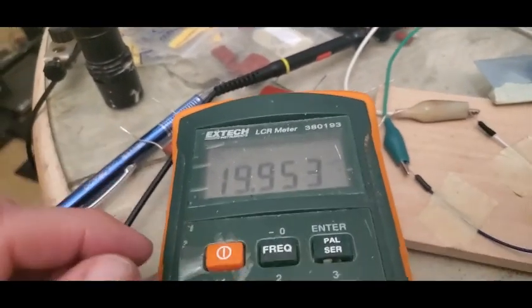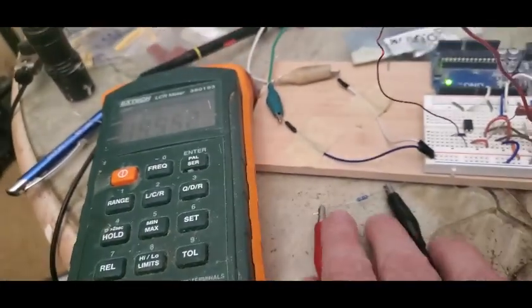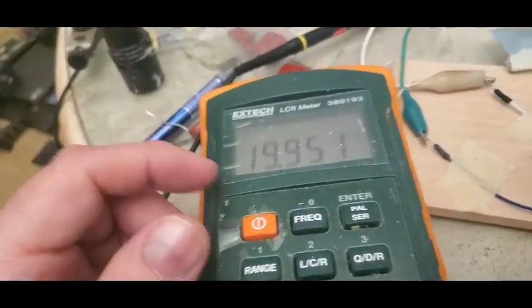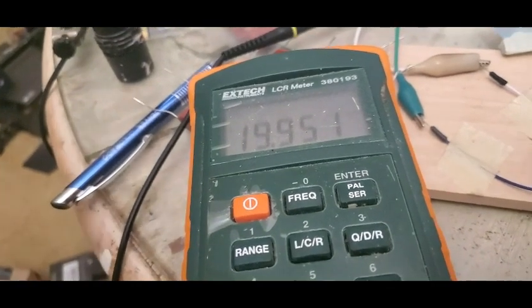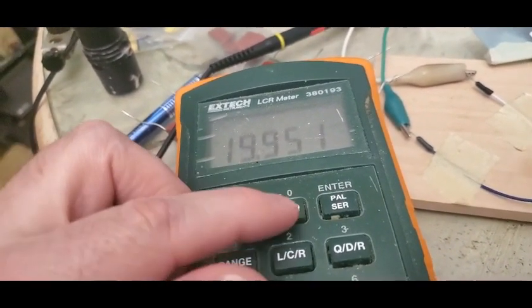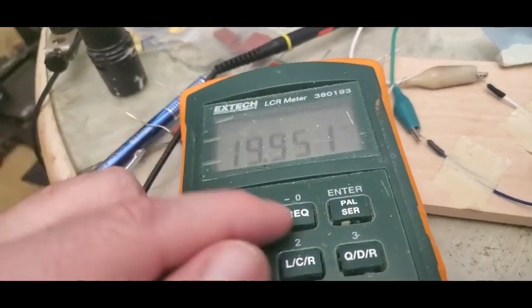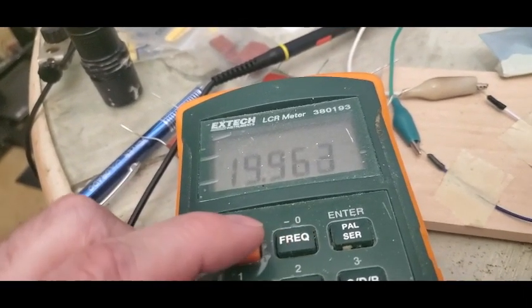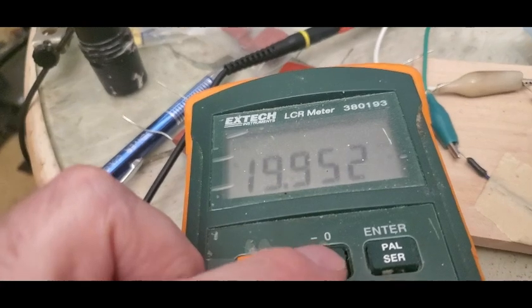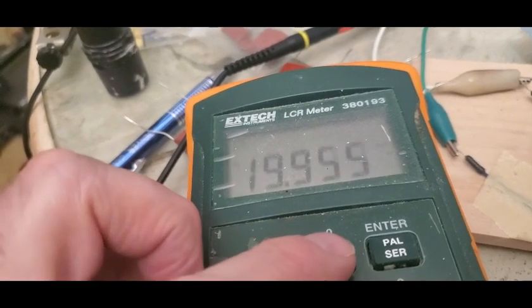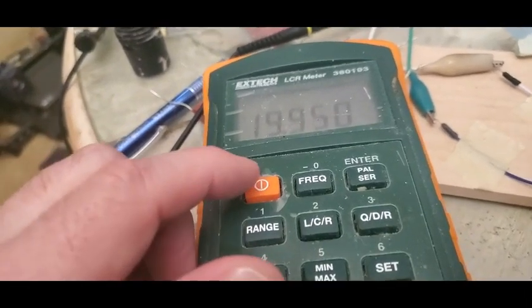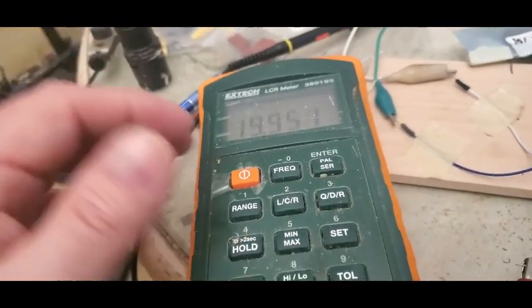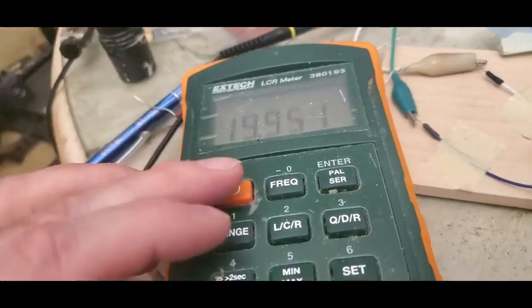So I have this LCR meter, and right now I have it hooked up to a resistor and LCR, so now it's measuring resistance, and it measures at either 120 hertz or the other is 1,000 hertz, 1 kilohertz, and you adjust with frequency. So the two values are pretty much exactly the same. However, I noticed with this thing, whenever I tried to measure the resistance in a coil, it would get all goofy.